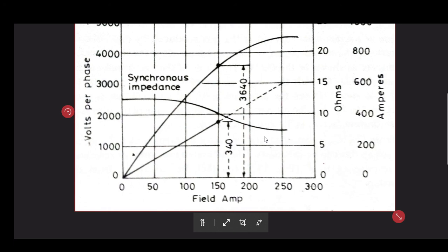by a virtual reactance. But as I have already mentioned, the EMF method generally works based on the linear region, where the OCC curve is very steep. Based on that region, it gives the regulation value, and that is why we are getting such a high value of regulation.